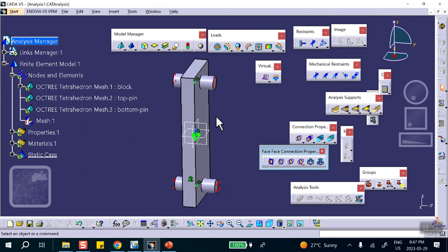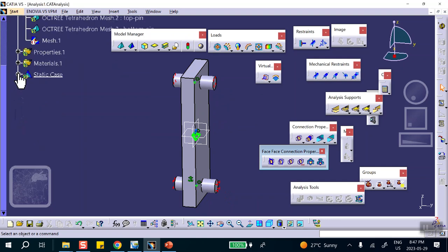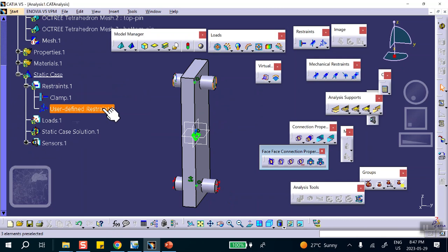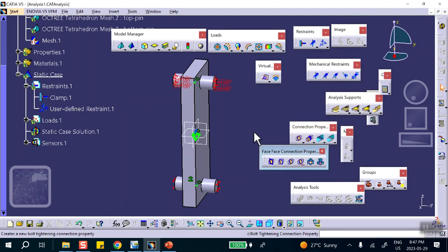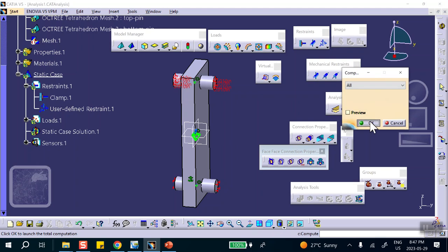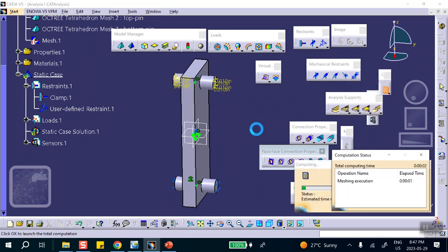Now that I specified my load or restraint, now I can go and change this, right? So we go here to enforce displacement. You remember that? You click on this, and it says how much? 0.01 positive, right? 0.01, 100th of an inch upward. It looks like everything is done, except that you will see that it will bomb out several times until we take care of everything. All right.